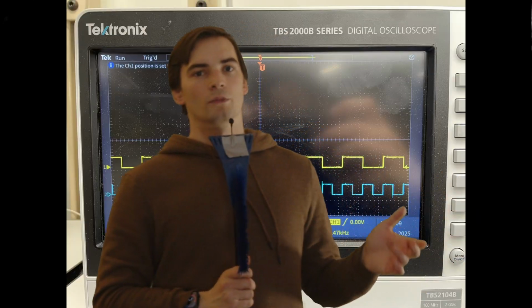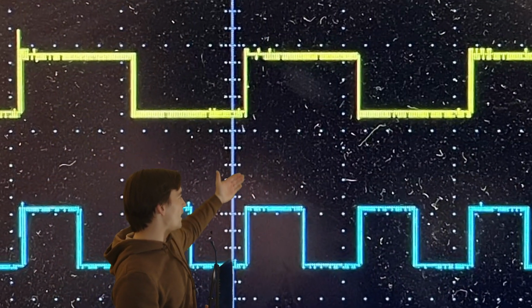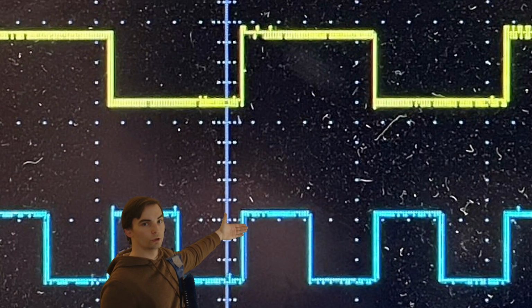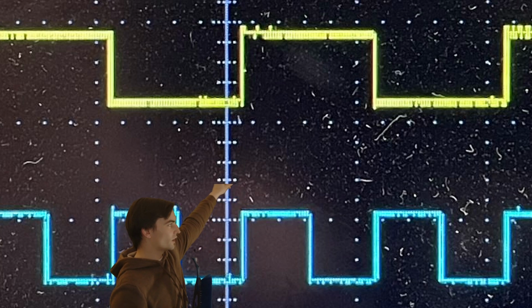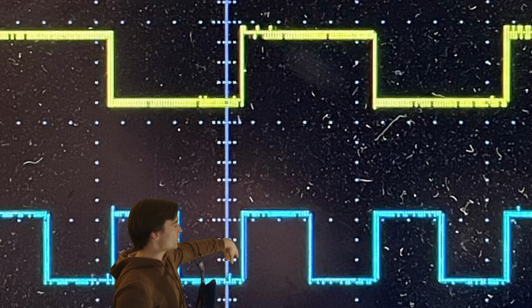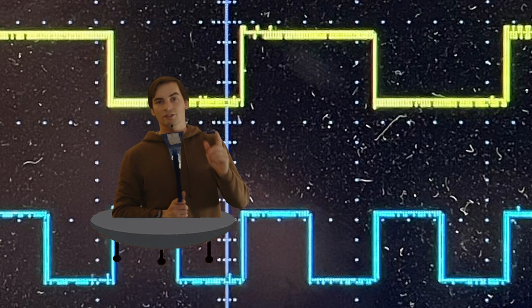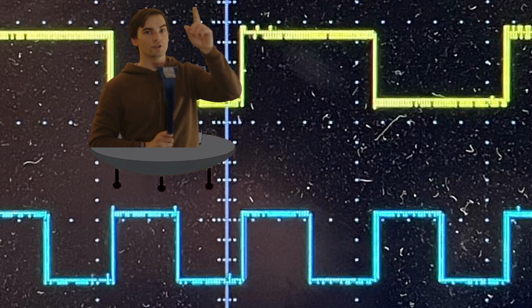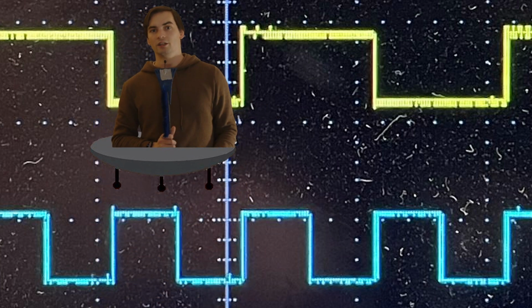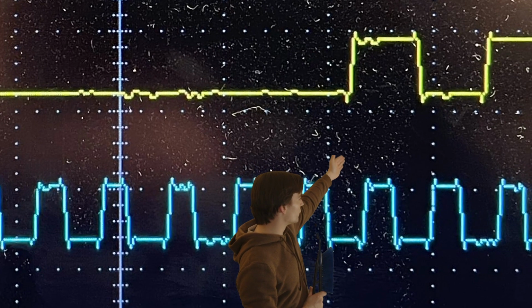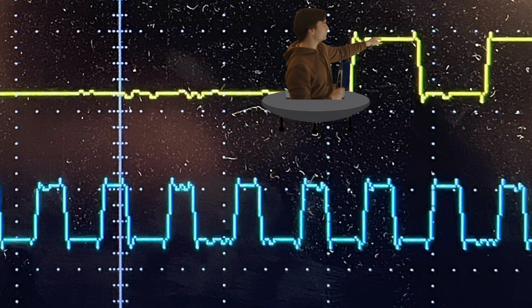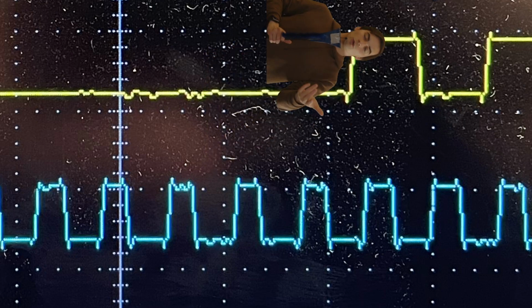So as you can see, what happens when we have this line here? Good question. That's the clock line. That says when you see this rising edge, meaning it goes up, you should check what the data is. And you can see that the data is also a rising edge. That's no good because that's undefined behavior. You don't know if it's going to read as a 0 or as a 1. You want the clock edge to line up with the flat piece, either at 0 or 1.